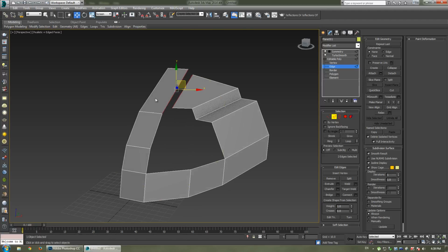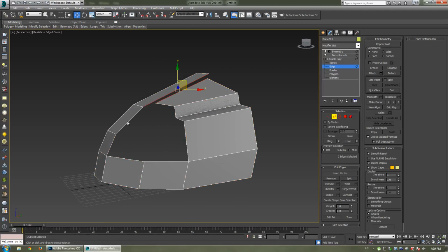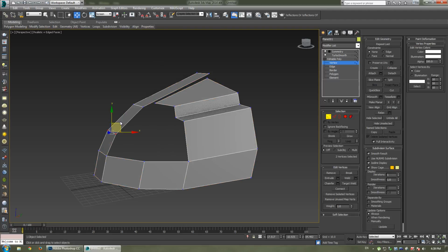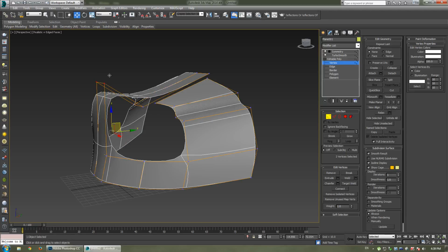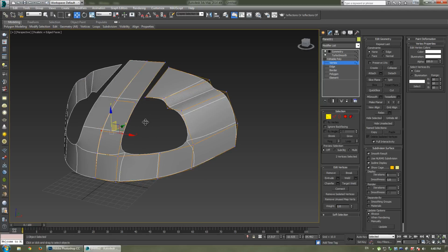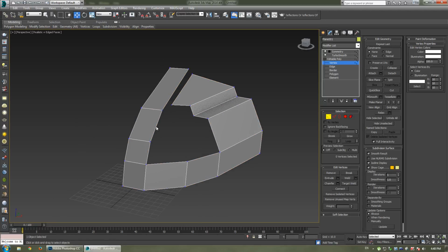So you can see here we've got three edges making up this curve. So when I go to adjust that curve, if I hold Alt and right click and go back to view mode, all I want to do is bring it up or down. Now while I'm modeling, you can see that I'm adjusting the overall shape of these curves. Now the hard part is, and I see it all the time when people are new to modeling, they add more geometry than they realize they actually need.